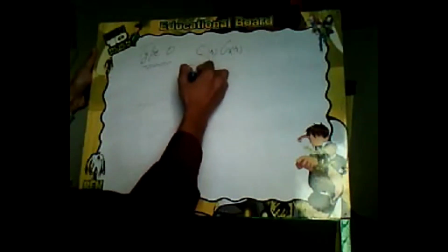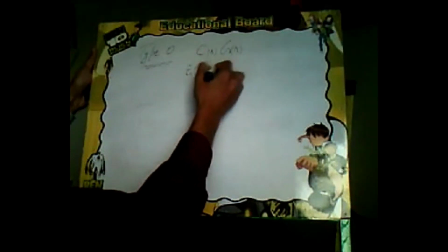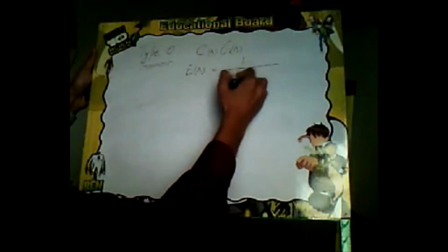If you apply s equal to 0 to this transfer function, nothing will happen. So c of s into g of s will be in general some transfer function which we cannot do anything about. So similarly, e of s will remain equal to 1 over 1 plus c of s, g of s.